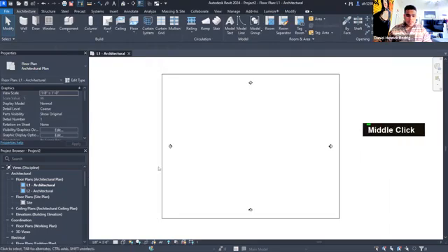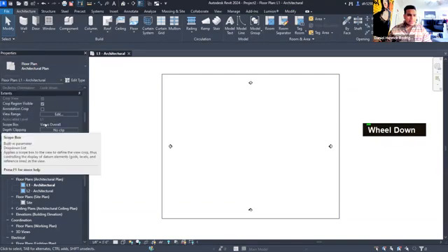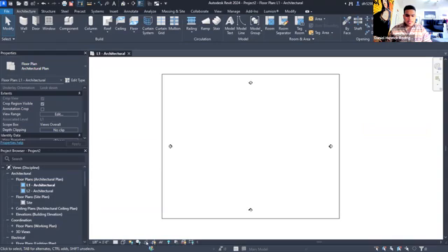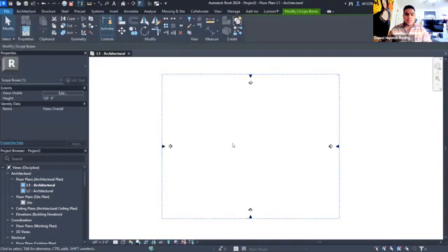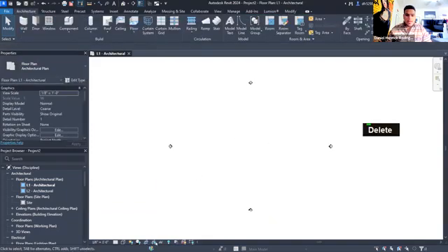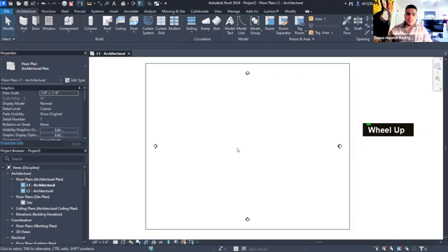There's also another scope box that's hidden behind this line. What we're going to do here is on the Properties tab, we're going to scroll down until we see Extents, and in scope box it says Views Overall. Now this, for some reason, doesn't let us use this tool here. This is a Revit 2024 thing, but to fix it, we're just going to change it to none. Now we're able to use this tool. That's for later, I'll show you. But we're going to use the hide crop region to get rid of that black box and then unveil this last scope box that was hidden, okay? I'm going to go ahead and delete that. And this tool, you can either leave it on or off. Doesn't really matter. We're going to be working inside this box, okay?